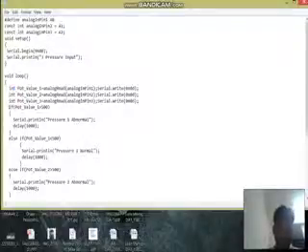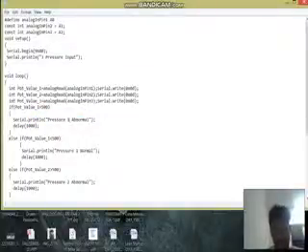As you can see over here, if port value 1 is greater than 500, then it signifies that there is some pressure on the pressure sensor. That's why the output will be the pressure in pressure sensor 1. The output is abnormal. This is the print statement where pressure sensor 1 output will be abnormal. And if there's no pressure on the pressure sensor, then it's an else statement, and the output will be normal in pressure sensor 1.